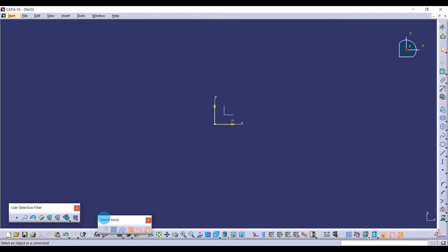So let's start with the Sketch tool. The second icon is the one having snap. So let's become close, snap to point, and these construction tools allow us to make a solid line into a construction line and vice versa. And we have something called geometrical constraint, and then dimensional constraint, and we have automatic dimensional constraint. And let's pull this out.